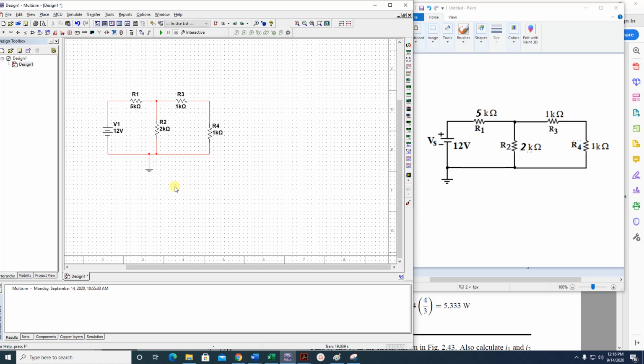Now, let's say that you want to verify Kirchhoff voltage law. Kirchhoff voltage law, it means that you want to put voltmeter across R1, R3, R4. I'm checking Kirchhoff voltage law in this loop, the outside loop. All right. I'm not doing this. I'm doing this. I'm doing the big one outside. Of course, it'd be easy. I just want to show you how you use it.